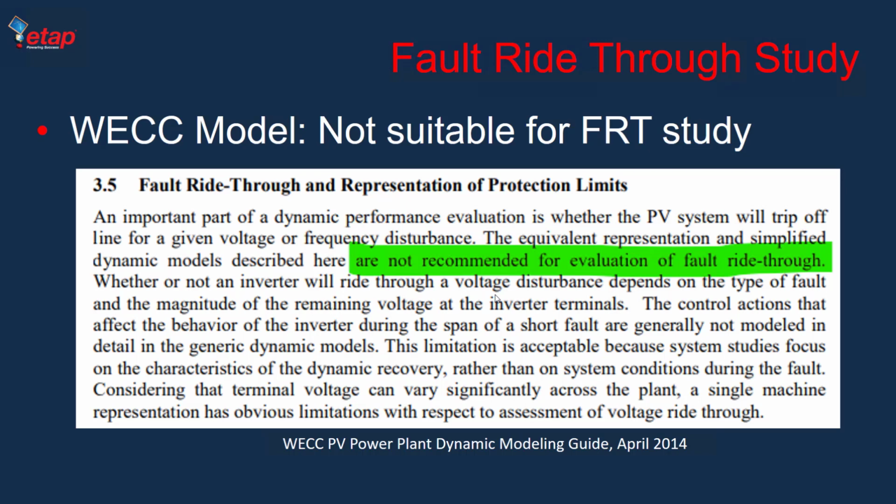So you're looking at overall performance of the system, you're looking at the stability of a big transmission system. When it comes to the interconnection studies, where you're looking at a very specific wind technology and vendor, and you want to verify that it's following the grid codes, it's very important to use the vendor model, and basically what the vendor does, to verify that the vendor is doing it correctly.